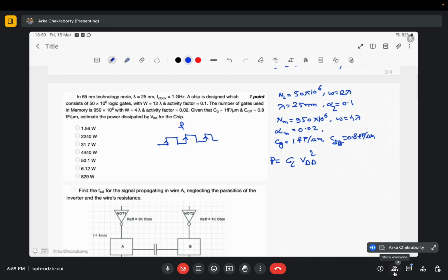The changes that have occurred during the rising edge or the falling edge, whichever my flip-flops are using, during this edge only my change in input would be captured as the corresponding change in the output. Okay, so my net power becomes linearly proportional to the frequency f. So power becomes P equal to CL VDD square f.